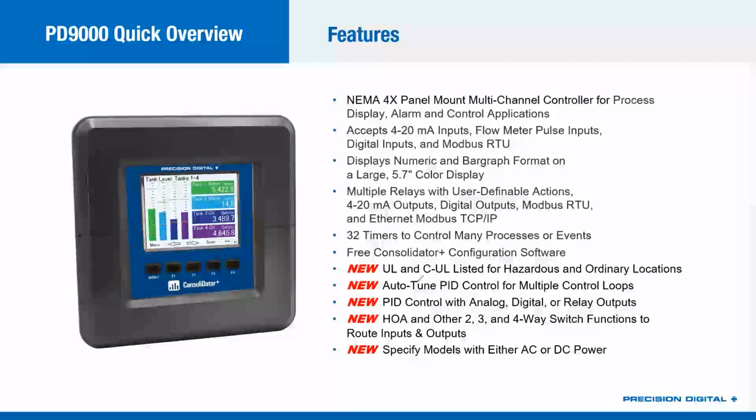We have auto-tuning PID control for multiple control loops. So this doesn't just replace one quarter-DIN PID controller. This will replace, I'd say, up to 8. You can go beyond that. It just gets a little tricky in the programming, but at least up to 8 PID control loops is fairly easy to set up, and we give you all the information on how to do that. And your output for your PID can be controlled via our 4-20 milliamp outputs, our analog signals, our digital outputs, or our relay outputs. So whether you're doing 4-20 outs to power controllers or pulse outputs from the digital outputs, or maybe you want to just have a relay tripping on and off on cycle time, time proportional, pulse width modulated type control, great, we can do that as well.